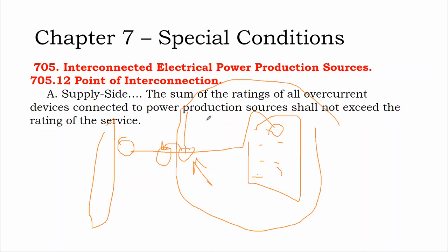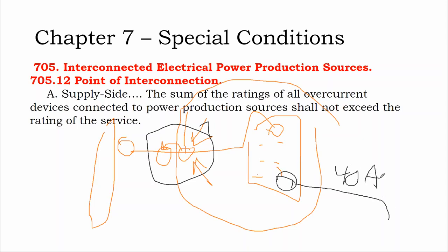You might want to put that switch right here, so that you can fully isolate the home from the grid. So if you're doing a supply side connection, I think you need to start thinking about automatic transfer switches for the whole house, and start building the infrastructure for whole house backup. Maybe not doing everything today, but at least putting in the appropriate disconnects and switch gears when you're already working in that area. And sometimes it's easier just to keep it simple, and for systems that are 40 amps or down, just land onto the service panel until you're ready to do something more ambitious.